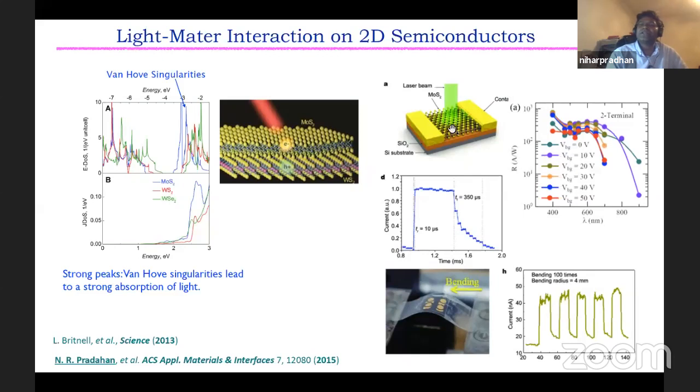semiconductor. So you can see here single atomic layer to few atomic layers of MoS2, which shows as a phototransistor or photodiode. Once you shine the light, it can generate the current, which is called the photocurrent. If you measure the photocurrent by shining the light, you can measure the responsivity here. The responsivity is the photo-generated current divided by incident optical power, and photo-generated current is the current with illuminated light, from which you subtract the dark current. Dark current means the current without the illuminated light. So that ratio will give you the responsivity of these materials, how this material responds to the light.